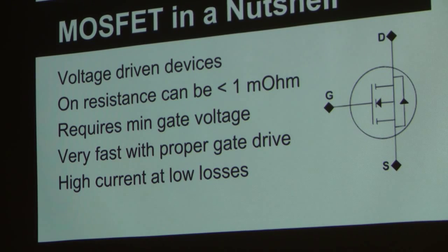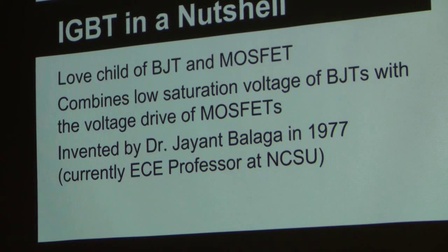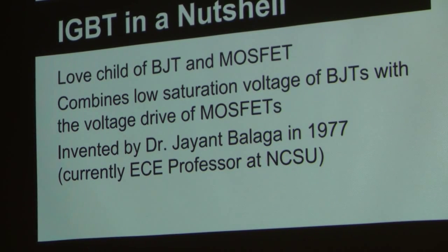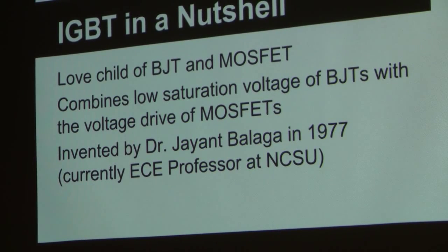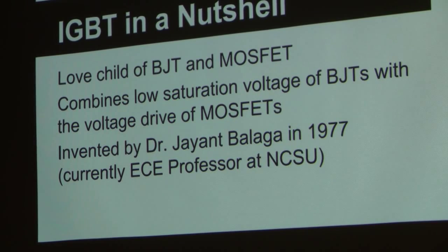Everybody knows the diode's there, so why do you care if it shows it? Because if it's not on the diagram, you can forget it's there. Instead of thinking, why am I seeing 0.6 volts across this MOSFET, if you look at your schematic and see a big diode there, you say, hey, I agree, 0.6 volts, that's a diode voltage. I think it's very helpful, especially if you're building H-bridges where those diodes are used.